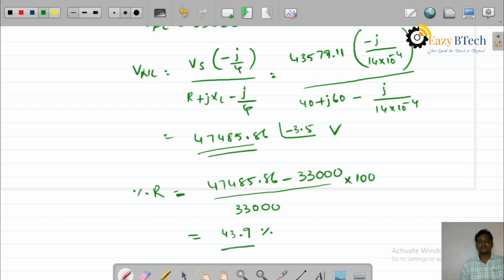Okay. From this load and condenser method, what you observe are the drawbacks of this method. Actually the capacitance is not completely concentrated at the load end. It is a wrong analysis, so we are having some errors in the results.